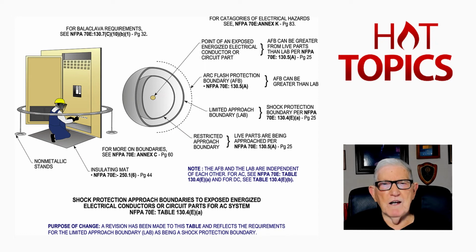And once you calculate that arc flash boundary, as I previously quoted, it may be a whole room. It may be a room of 20 foot. And once you unlock the door and walk in, you need your PPE on if you're going to remove covers and do switching on devices that haven't been maintained properly in the normal operating condition. You would need to wear your PPE.